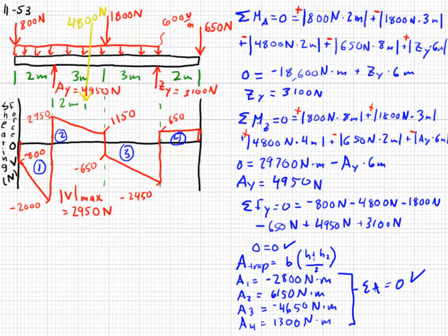So we continue on with actually constructing the bending moment diagram. In the same way we made the shear force axes, bring down vertical lines for the critical points.